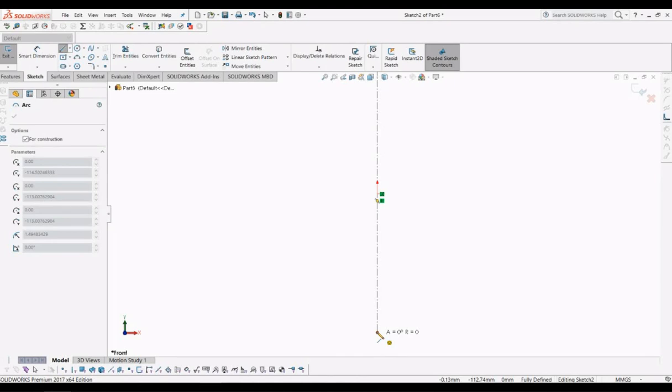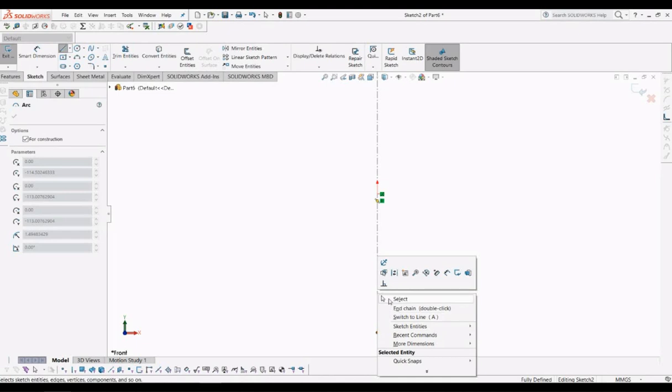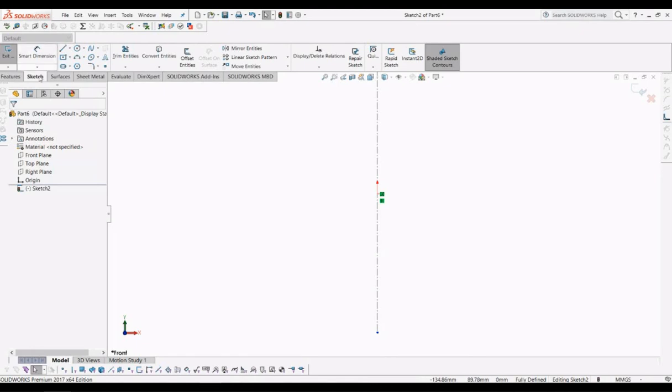After we see the color of the point change to orange, we can right click the mouse, then just select it. It means you select the point and you finish with your center line. So just click select, then everything went off. Your property manager turns back to normal, and in your sketch toolbar you can now see the button for your line is undone. Okay.